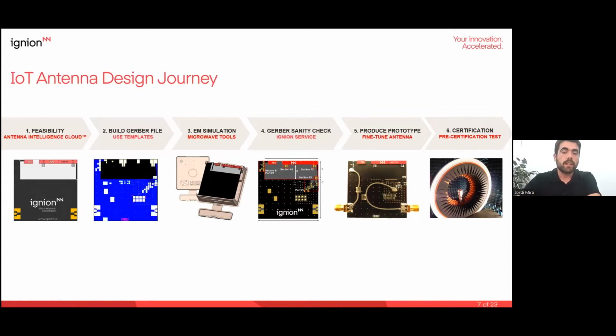And thanks to the electromagnetic simulations, you can put every component in your design, such as batteries, antenna location, and other RF components such as the RF module, connectors, and so on. So once everything is aligned with your expectations, the performance is okay in terms of simulations and everything is included and considered, you can go to the prototyping stage.